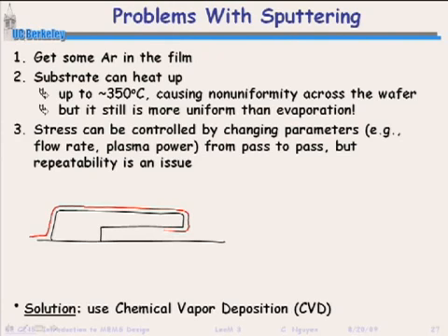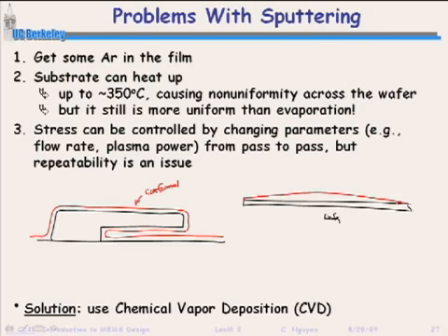Sometimes it's futile to use the equation, because if this is your wafer here, and you want to deposit a film on this wafer, the ideal case, of course, is where the film is exactly the same thickness throughout that wafer. But what really happens is the film, depending on your deposition, may look like this. Maybe thicker in the center than on the edges, and maybe thicker on the edges than in the center. Okay? And so this is something that's non-uniform.